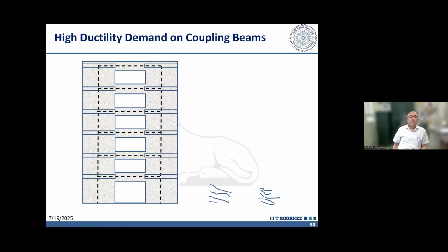Now, in a coupled shear wall, we can consider that the vertical shear walls are like columns, and these beams are connecting these wide columns. And any section of these columns, including the one which is connecting with these beams, will remain rigid, plane, and perpendicular to the neutral axis after bending. So when the shear wall will be subjected to lateral load and it is bending, we can see that this section here, which was perpendicular to the original axis of the shear wall, will be perpendicular to this new axis of the shear wall.